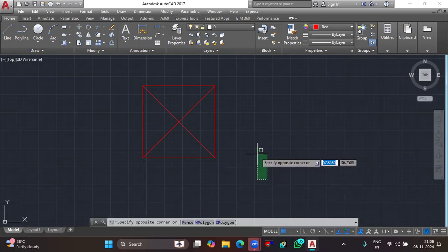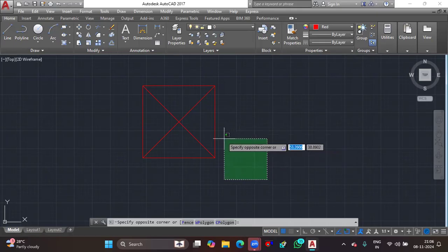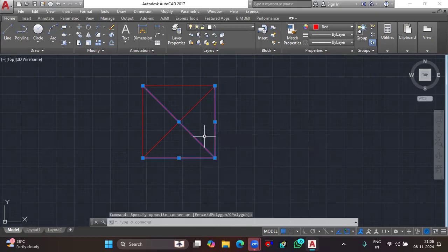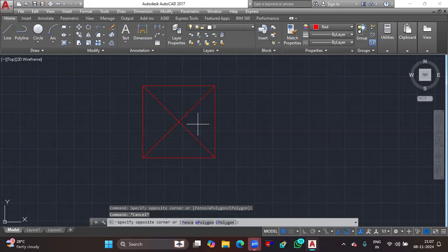But if you do the same from right to left, then it is meant to be green selection. You can see right to left. So at this instant, I'm not covering the entire object. Instead of that, I'm just selecting these 3 lines. You can see not covered it fully, but still it's got selected. So that is the concept of this green selection, which means if it makes a contact with your selection, automatically the entire dependable object should be selected. Okay, clear, guys?